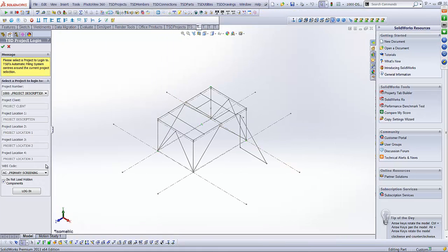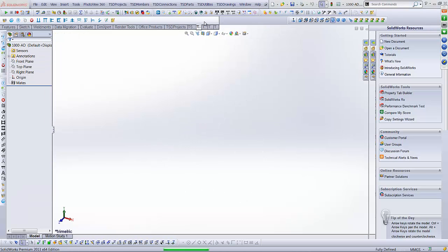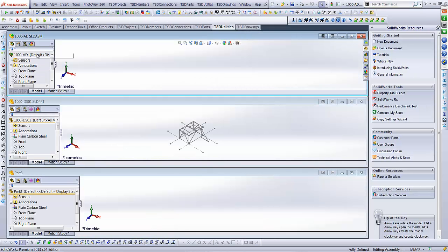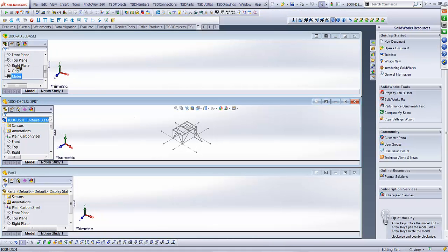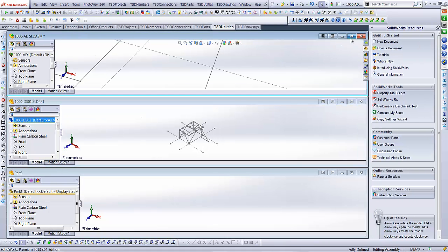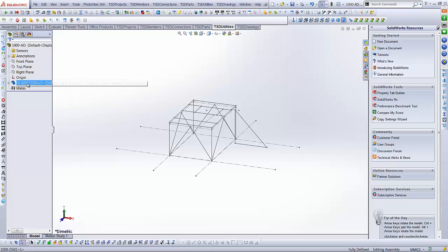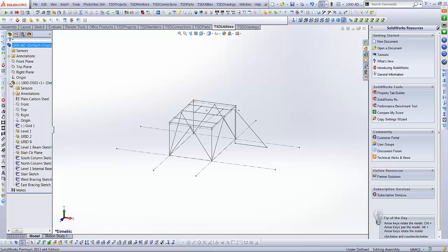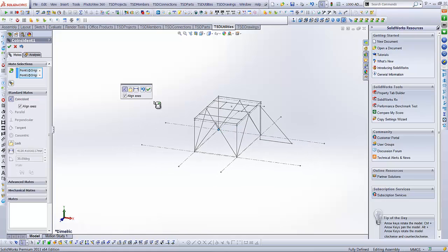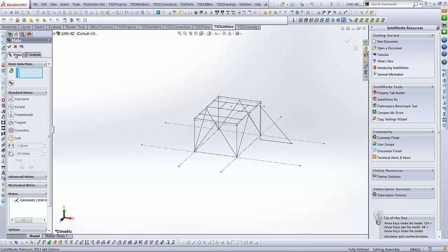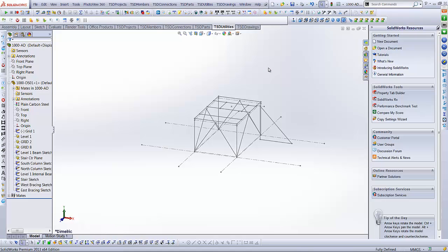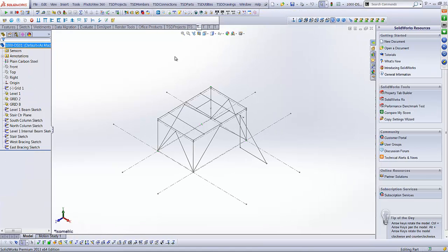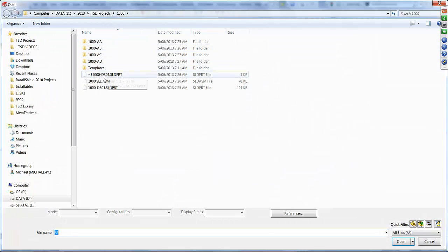And last but not least, we log into area D and do the same thing there. Float that and grab the origins as well, and the paperclip comes up there as well, so you can use that. Align axes, hit your tick. Okay, now we've got one more place to put this, and that's at the top level assembly.